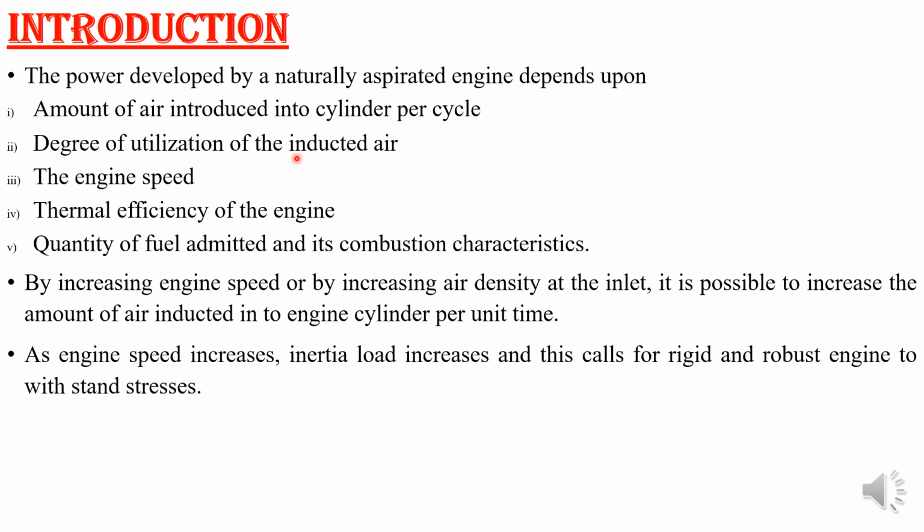So this is how engine speed can be avoided. Also, as the engine speed increases, there is less time, hence the amount of air introduced inside the cylinder may decrease. That means volumetric efficiency might decrease because of higher friction or bearing loads. So only one possible way is left to increase the power without changing much in the engine component size, that is, increasing the amount of air introduced inside the cylinder.